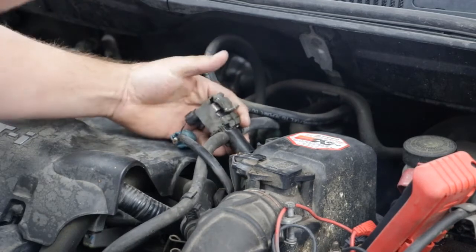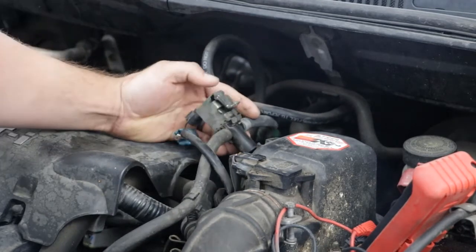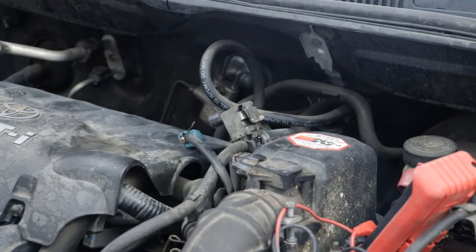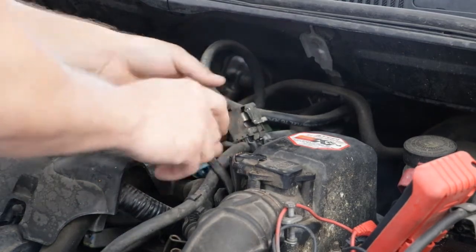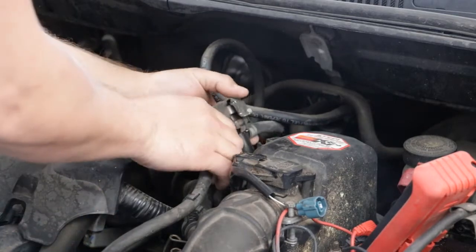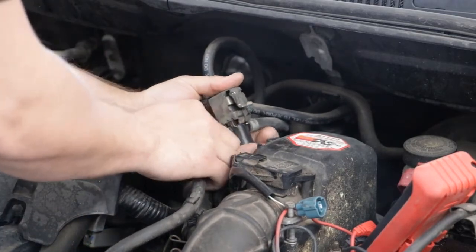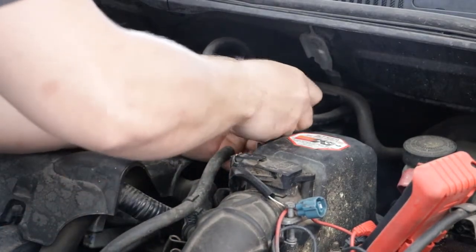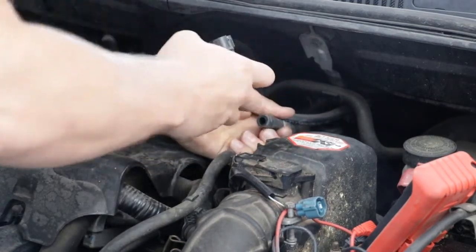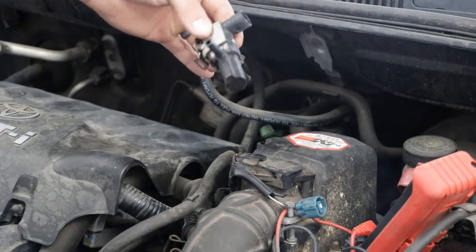So once you get it out, we're going to go ahead and take off the purge valve. We're going to test the solenoids and make sure there's a seal. It shouldn't allow any air or vacuum to go through it. So we're going to take off these hoses here, move our broken electrical connector out of the way, and then gently pull this off. This one does have a little clamp, but it's not very strong. And there we go. It's pretty simple, two-part.